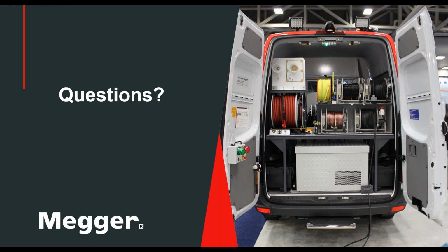But as a side note, if you will, the unit's range is worth a shot using because you don't know the breakdown voltage on these 69 to 230 kV cables. We've had multiple customers who have tried using these ST25s on these higher ranges, and depending on what it actually breaks down at, if it breaks down earlier than 25 kV, you can use this unit.